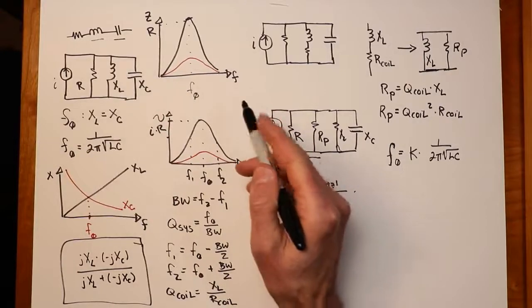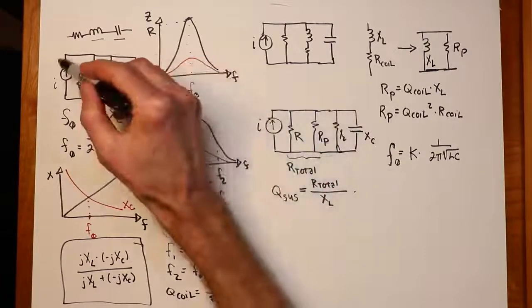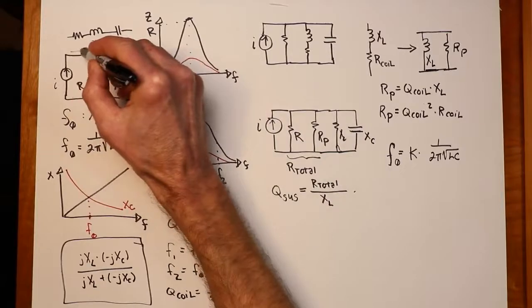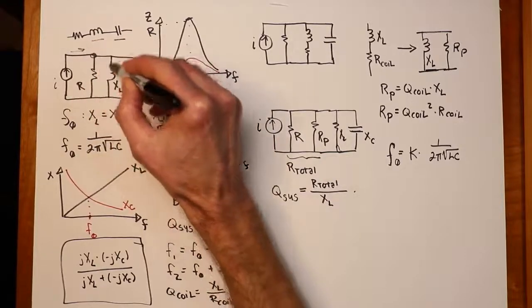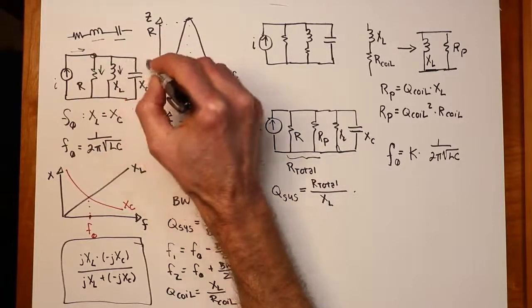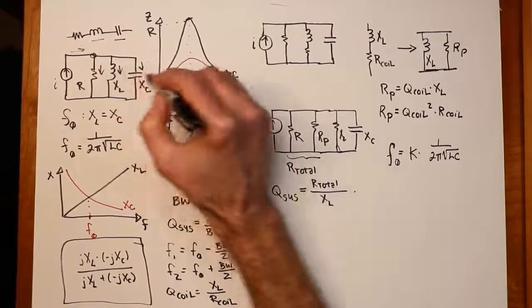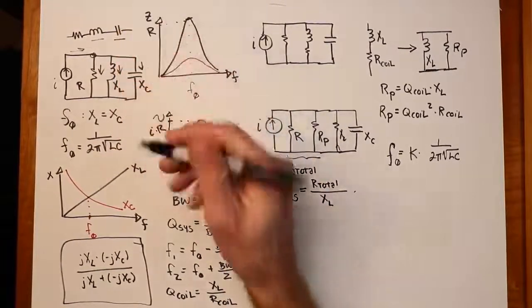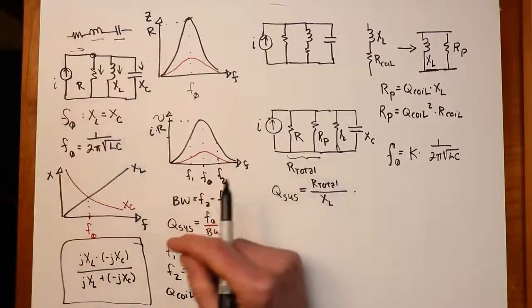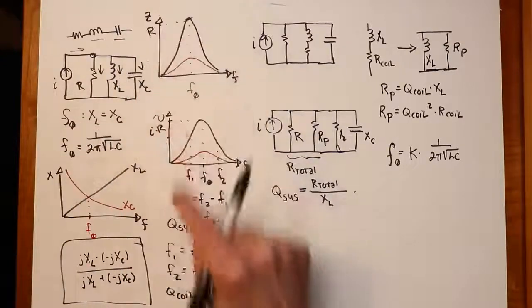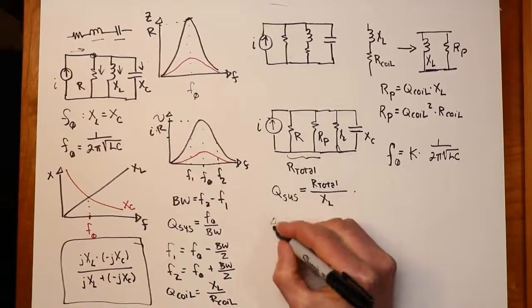So what does that mean? Kirchhoff's current law says, look, what's coming into this node, this current coming in here, that's going to split 3 ways. Right? Simple reference directions. But these 2 things are actually in anti-phase. When the current's going down in the inductor, it's going up in the capacitor, right? We have sines.